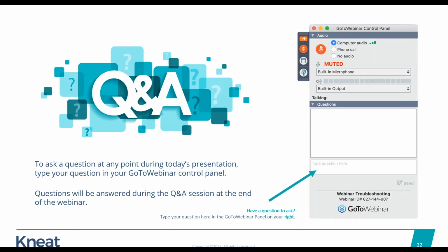But the first question I see here coming in, Olivia, is it common practice for there to be 3 PPQ, the process performance qualification batches, manufactured during stage 2? Sure, that's a really good question. So it is common for there to be 3 batches, but there was also a recent change in the regulations where if you can prove that your process is in control without doing 3 full batches, that is something that can be done now.